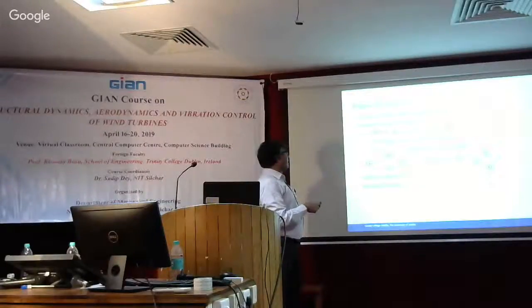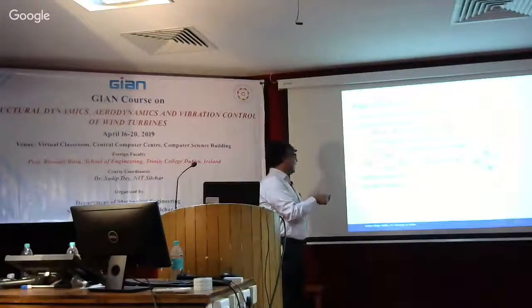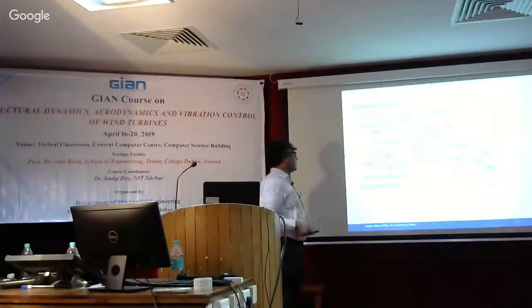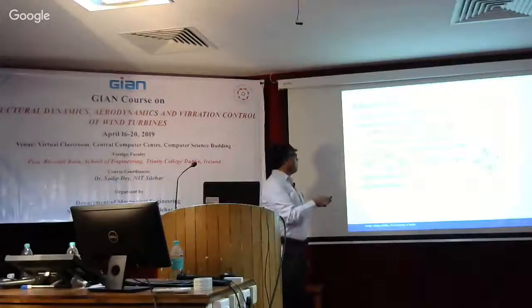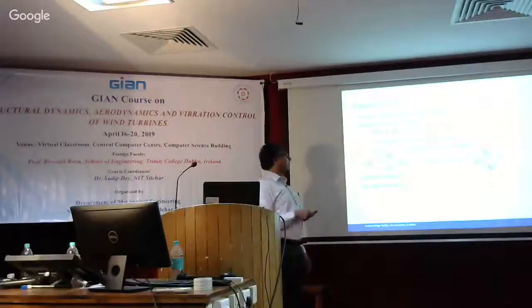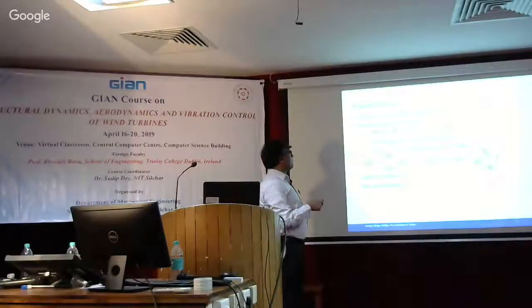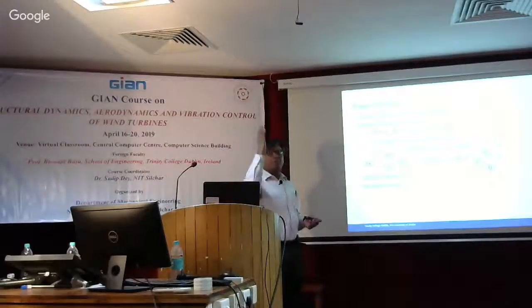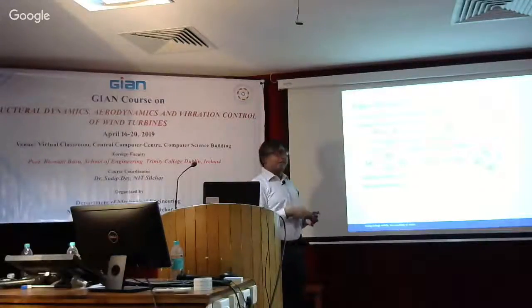So to find that, let's see what impact the delta F will have if we change delta beta, or the change in the angle of the pitch. So this is the rate of change of the force with the rate of change of pitch angle. So if I change this by delta beta, then this is actually the delta F. And we have to make sure the force is something like minus d_p x dot, which is the damping that will be added to the tower. So using this expression now, we can find delta beta, which is the change in the pitch angle. This is what we really want to know, because how much is the angle we have to change so that we get sufficient damping.